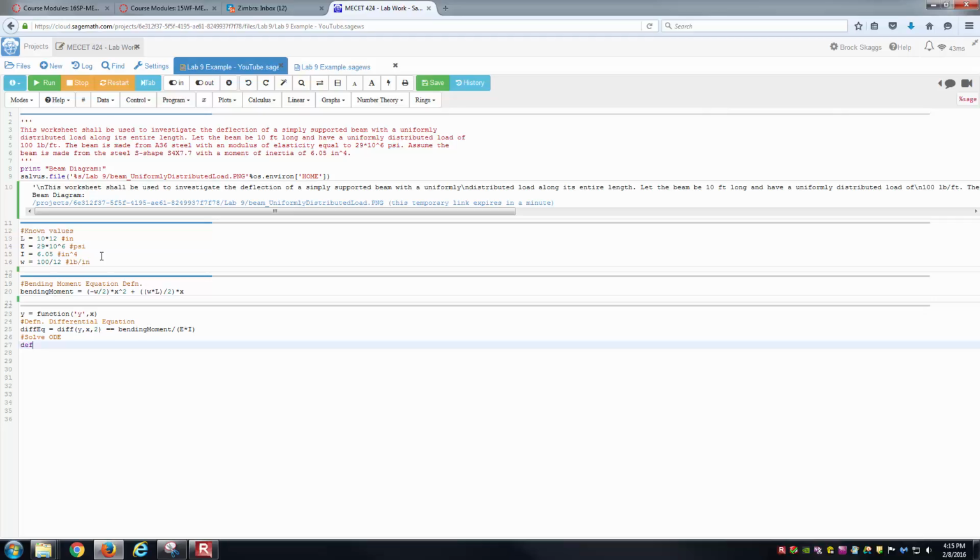And so using that, let's calculate the deflection. Notice it's DSolve here. And so just hitting DSo, I'll hit tab there in order to bring up my list. There's DSolve. There we go. And then inside of the argument, so what are we passing? Well, we're passing the differential equation, so diff eq. What we want to solve for is the next part. So we want to solve for y, comma, and now we want to express the conditions for our particular solution inside of square brackets here.